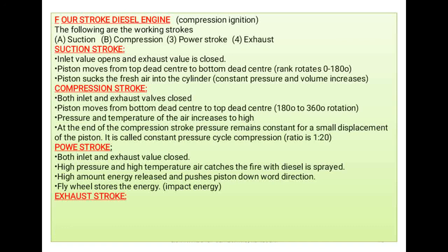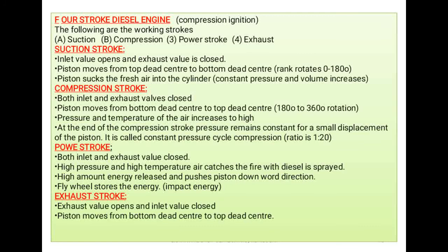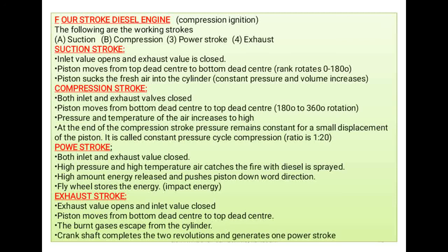Exhaust stroke: the exhaust valve is open and the inlet valve is closed. The piston moves from bottom dead center to top dead center, and the burned gases escape. Due to the piston movement, the volume keeps decreasing inside the cylinder, so the burned gases escape from the cylinder to the atmosphere through the exhaust valve. Again, the crankshaft completes two revolutions for making one power stroke.